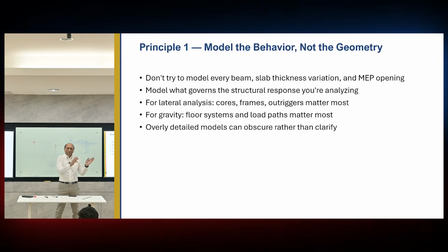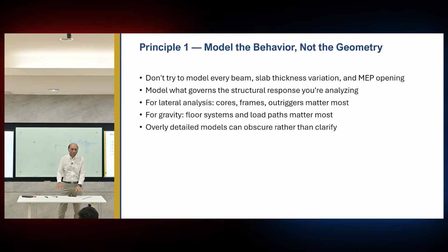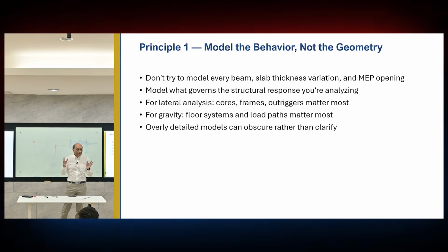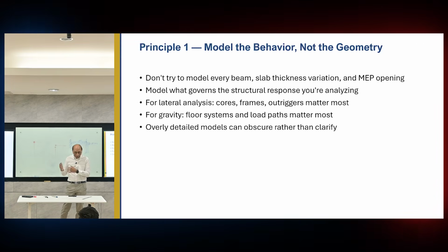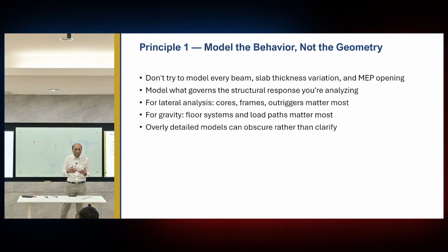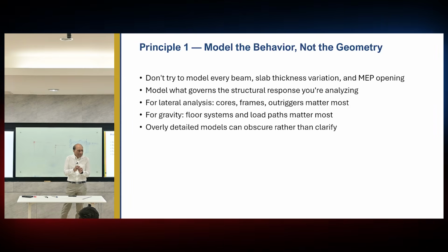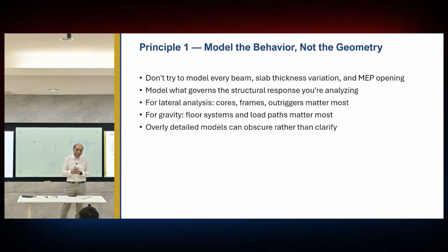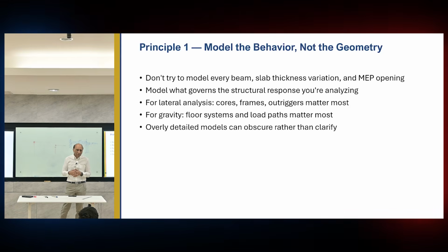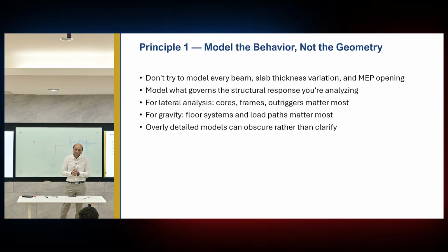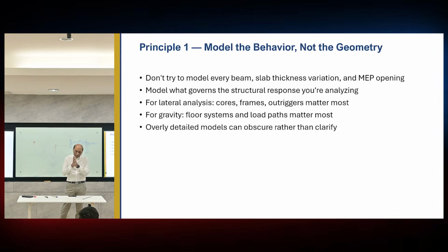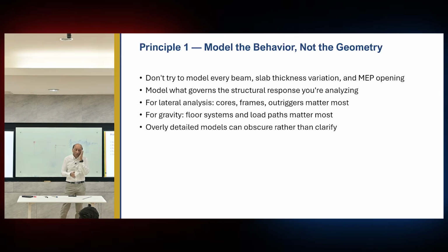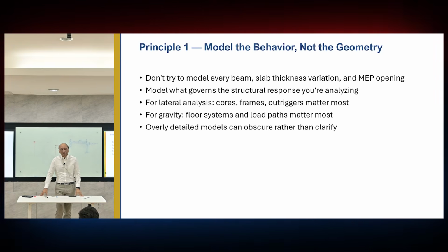And then when you go to lateral load analysis, they don't need to worry about the floor details. They just model the primary things, and it's perfect. Now ETABS can do both. So now people make a 40-story building with very fine mesh and openings and all, and then they say they cannot run the program, or it's too much data, too much output, because they didn't make the decisions to just model what they want. So for your project, you must make sure that you make the right decisions on modeling.